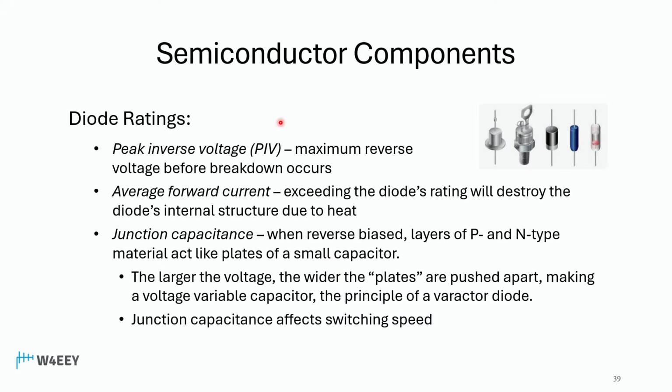So diode ratings, I don't see any blue text here, but it's kind of nice to know some of these things because you're going to be running into them. I suppose we could have called this slide how to blow up a diode, okay? So let's talk about that. Peak inverse voltage, okay, this is the maximum reverse voltage before breakdown occurs. So the diode, here's a bunch of different appearances of what you might find.